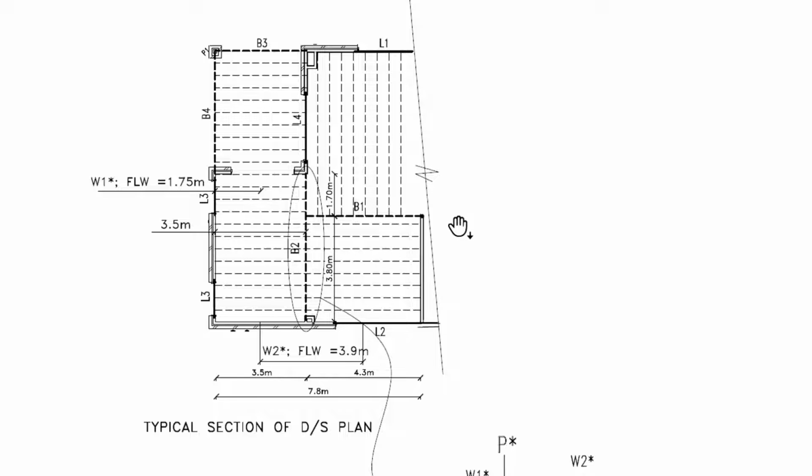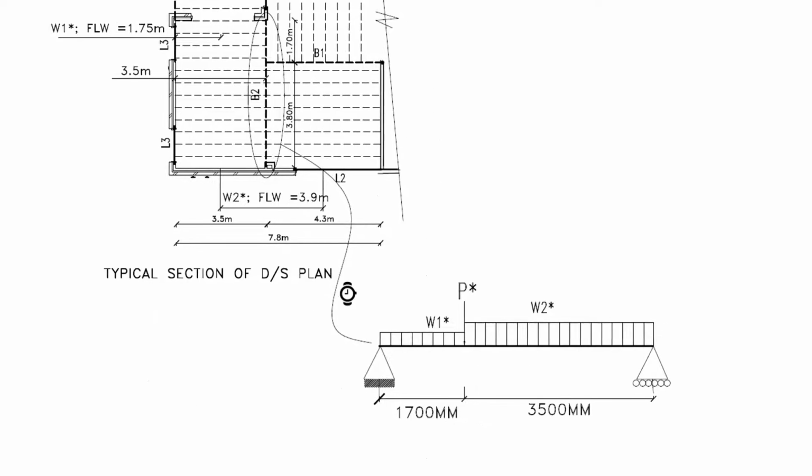Now, have a think of why I numbered the beams B1 and B2, or why have I drawn it up that way, that particular configuration. Well, very simply put, to design B2 we need to first design B1, and hence this is why I drafted it. So then the engineer who's checking the job and is going through the documents would first go through B1, find out all the reactions, and then take it down to B2, and that quickens the process of design, and there'll be minimal errors. Okay, let's get straight into it.